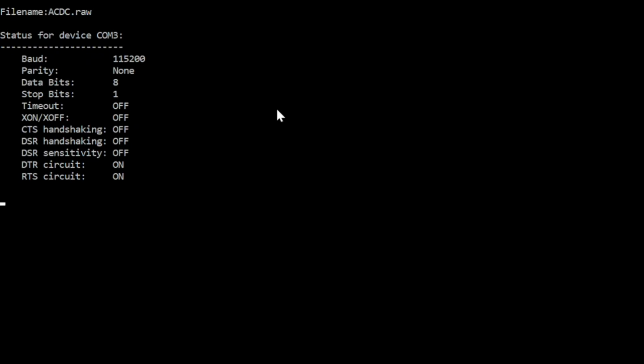So that's what it's doing right now. If I put the headphones onto the microphone, you'll be able to hear what the computer is doing. It's just taking the byte and sending it straight to the audio output register. I've resampled the actual file so that it's only 8 bits instead of 16 bits like the original one.